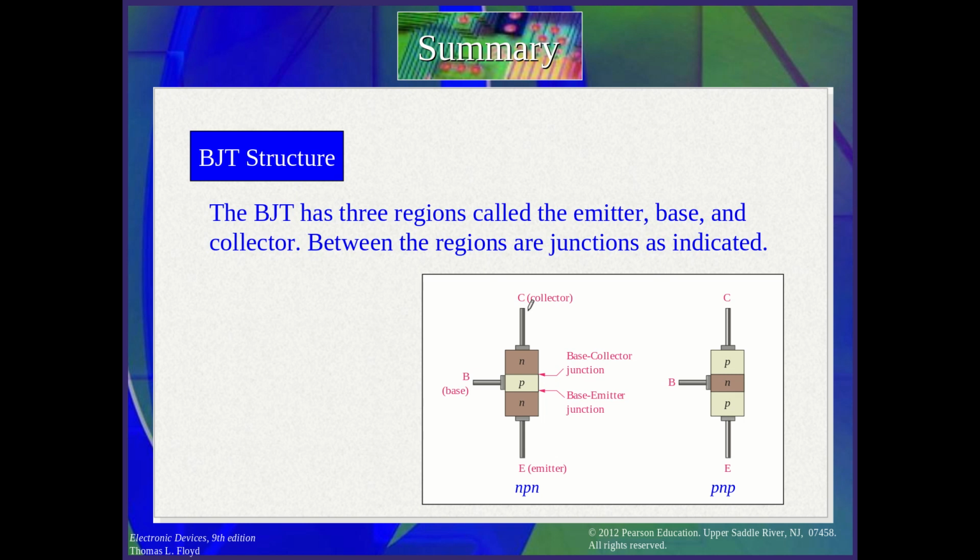Where there is a voltage here and current here, there is a forward bias, and my transistor conducts, and there is an IC that comes across the transistor, then we use it as a closed switch.